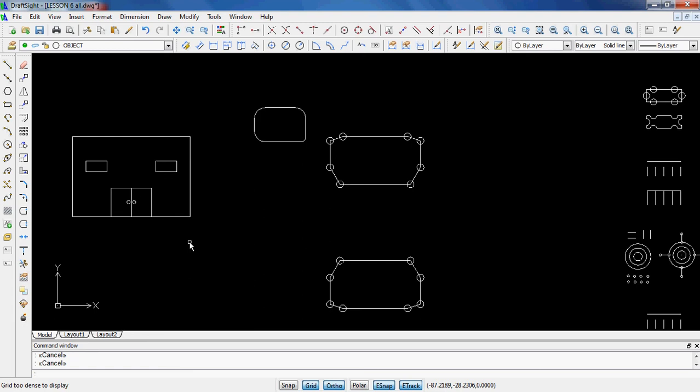So that's fillet, that's chamfer, two different methods of chamfer, which is the distance method and the angle method. I showed you a new method of copying, where you can copy multiple things, and then finally the mirror command. And now that we're up through lesson 7, using trim and extend and mirror and all these different things, you should be moving fairly quickly through your drawings because you've gotten to see a lot of the most used commands so far. There's really one other one that I want to show you that will make you a lot faster.